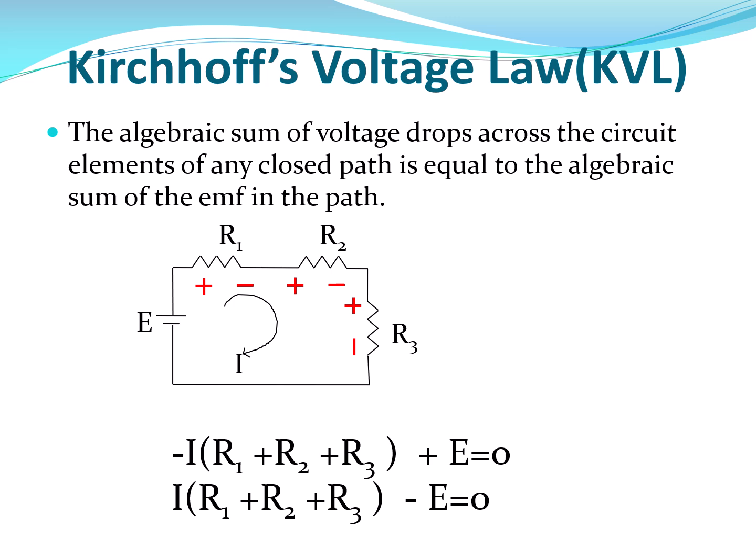Now, while we apply this KVL in our circuit analysis in future, no need to consider the first one, you only have to remember the second one. You consider the direction of current, and you also move in the same direction. Whatever direction you choose for the current, in the same direction you will move in the loop.